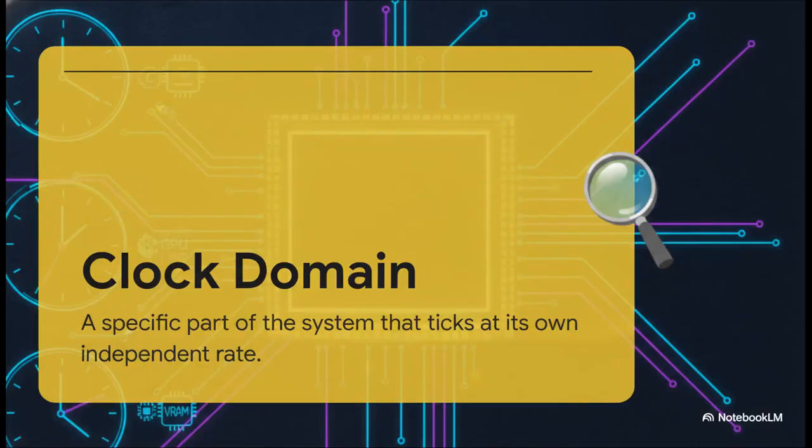When we throw around the word clock in this context, we definitely aren't talking about a single overarching speed limit for your entire computer. No, we're talking about different clock domains. Think of a clock domain as just a specific part of your system that ticks at its own independent rate. Your CPU has a clock. Your GPU's streaming multiprocessors, the SMs, have their own clock. And the GPU's memory, the VRAM, has a completely separate clock. So you're never really looking at one master GPU speed. It's more like several distinct domains working together. And actually, moving the data around takes time too, not just crunching the math, which is exactly why that separate memory clock is so fundamentally important.